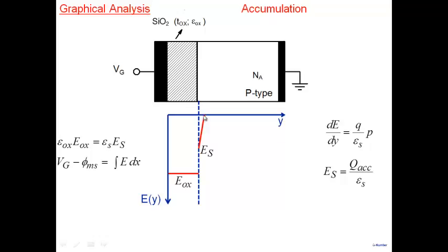So it's very thin. So we ignore the drop here, and when we take it, then Vg minus phi ms equal to the drop here is Q accumulation by C oxide. And if you want to be accurate, you can say the drop here is nothing but the surface potential. But we are saying surface potential is practically 0. Very close to 0 here. That's what we are saying. The drop here in this is close to 0 here.